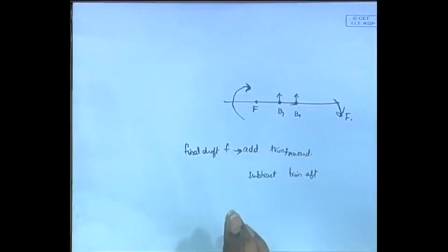That is plus always, okay. That is an increase in draft. You can see it's an increase in draft. Similarly, trim like this means here it's an increase in draft, here it's a decrease in draft. So here it's plus, here it's negative. So in this particular case, the ship trims like this, and so this you have to add. This is how you find the draft forward and aft. At forward you add it, and at aft you subtract it. This is what happens when you have density change. That is one possibility.